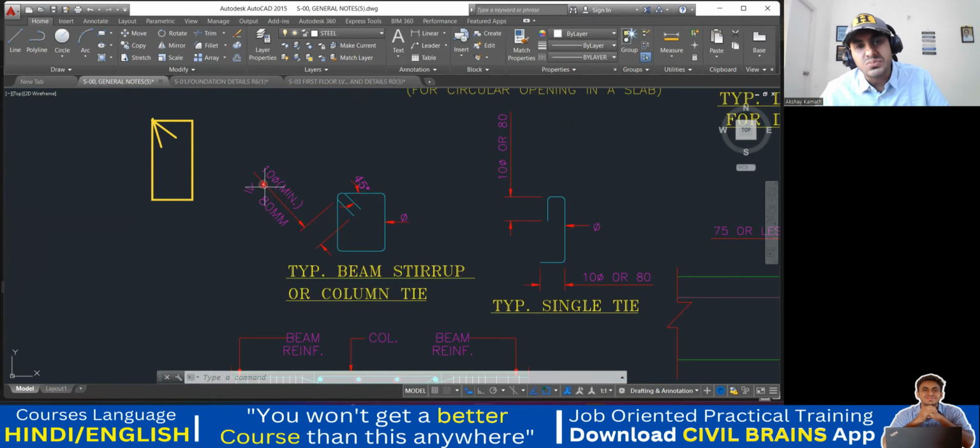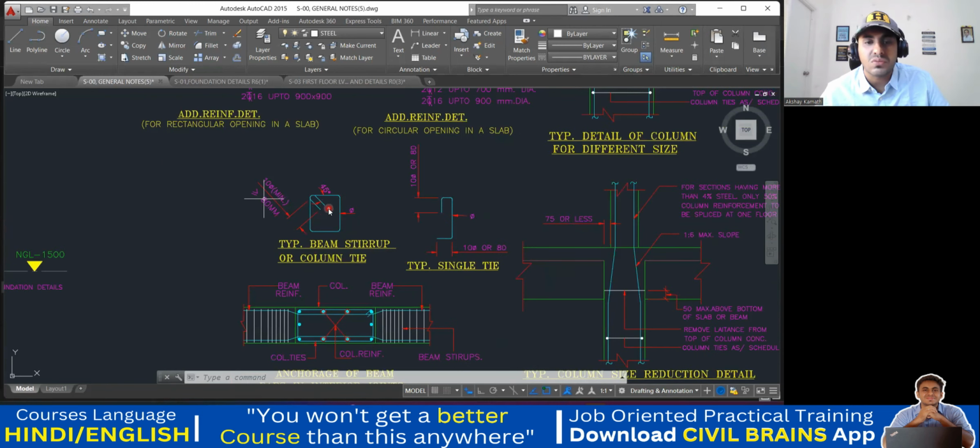Here he is telling 10 times the diameter of the bar, and for minimum, greater than or equal to 80 mm. Here instead of 75 mm, he has taken 80 mm. Maybe he has taken it from the code book. But usually it was actually 75 mm. Maybe now they have made it 80 mm. Not an issue, because 5 mm doesn't make any difference. So this hook length you're supposed to keep minimum 75 mm or 10 times the diameter of the bar, whichever is higher. Got it? Which you already know. But you need to remember all these things because in the interview they will ask you all these questions.